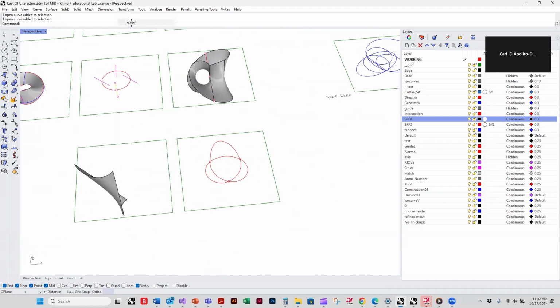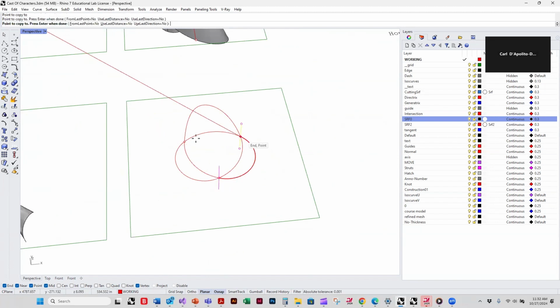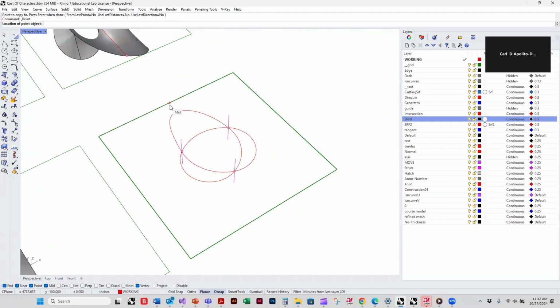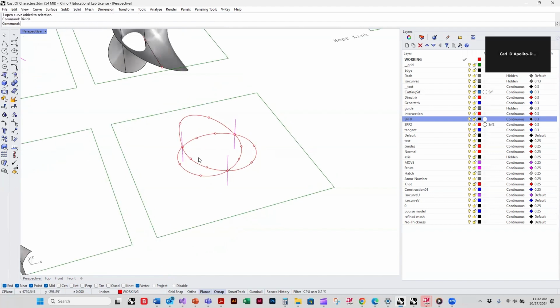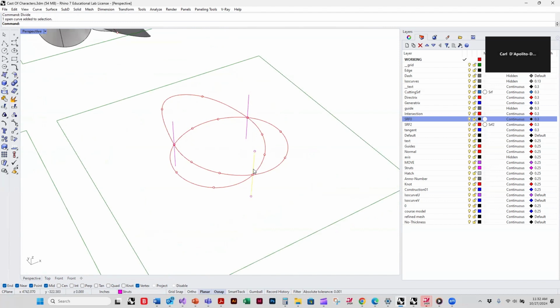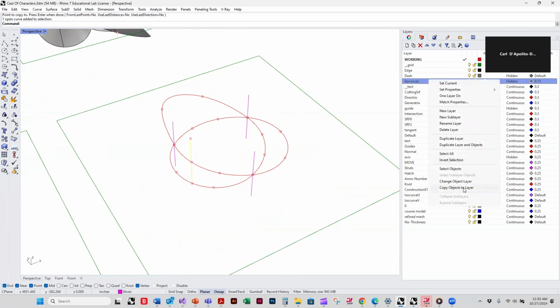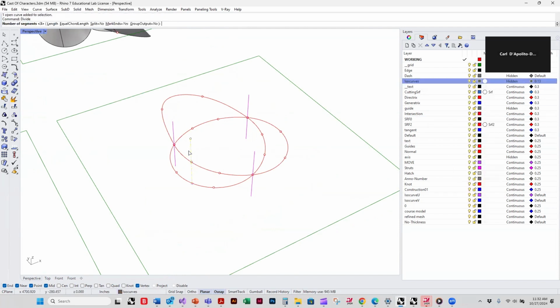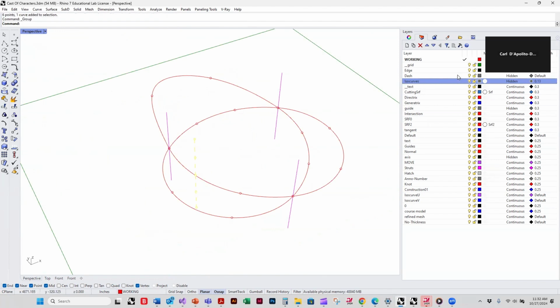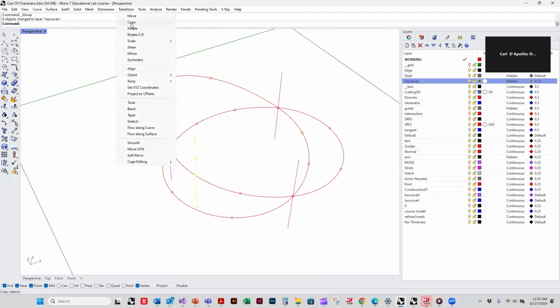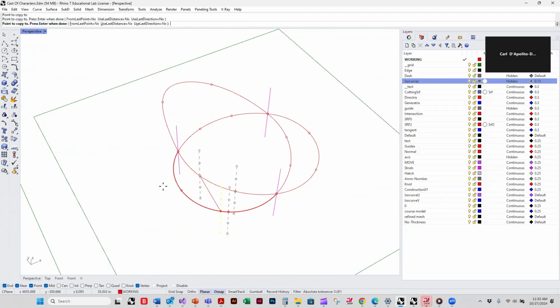Okay, so then I'm going to mark these points, struts, and then I just need some points along here that I can use. So I'm going to do 3 points along each one. And then the thing is, I want to make sure that I'm going to copy the strut, divide it into three, and place it at all these points.